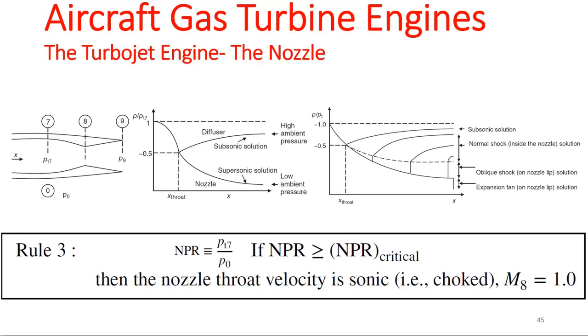Which part of it doesn't make sense? I just don't like when you say it depends on backflow, I like to think that it depends on the exit condition at the mouth. Not backflow, back pressure, right? Back pressure essentially means the pressure before this station, right? If you have a high back pressure, you have a high ambient pressure as well, which is your exhaust pressure. Does it make sense?